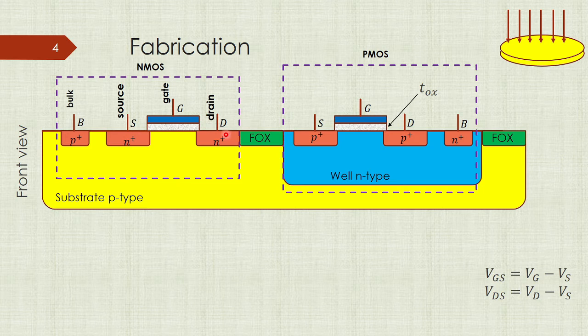Between the source and the drain, we will insert an oxide here, which will work as a dielectric, and above the oxide we will grow polysilicon, which is a conductor material, so that we can generate a capacitor between them. This capacitor will try to attract electrons close to the surface of the oxide.